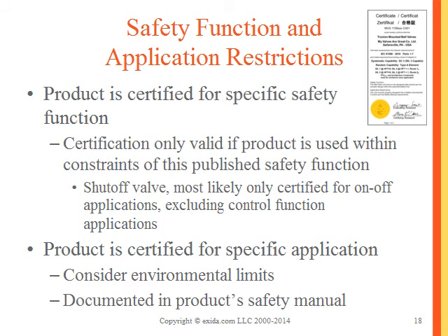But any restriction, and there could be environmental like here, or if you have a logic solver, maybe your AND and OR blocks and your function blocks are part of the certification. Your add and subtract blocks are part of your certification, but some complex logic block may not be part of the certification. So the safety manual will list all the components that are part of the certification, or all the options that are part of the certification, and also how you need to use the product.